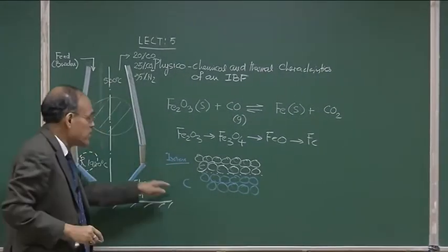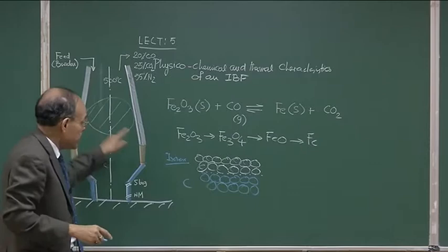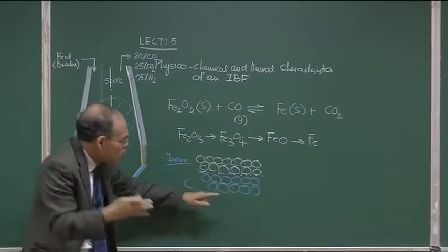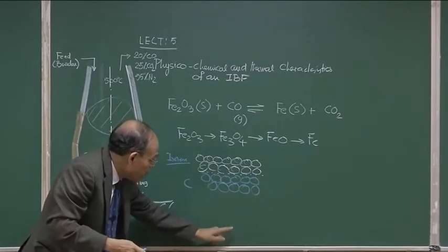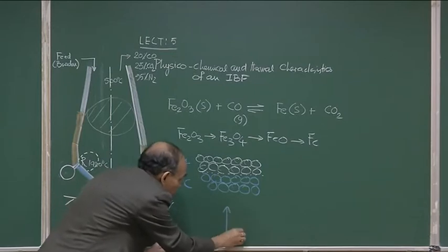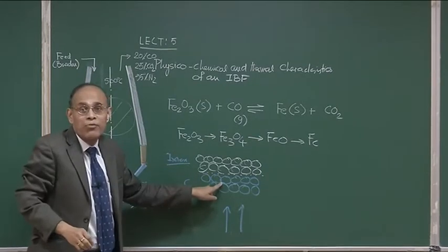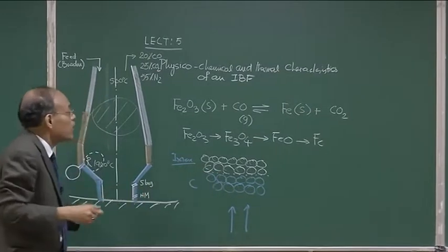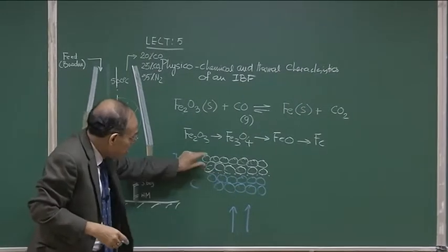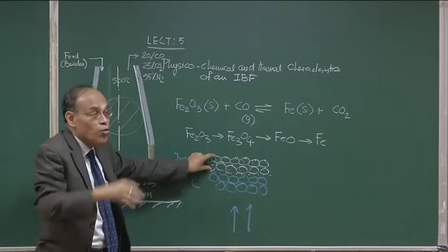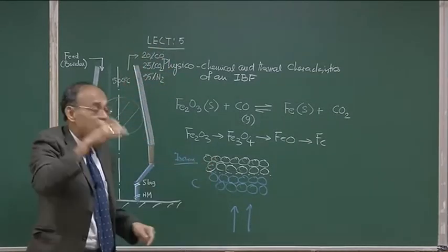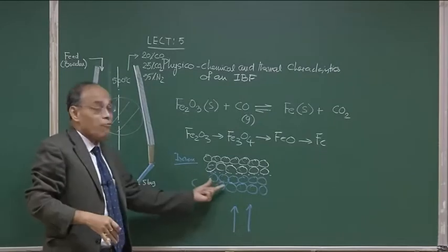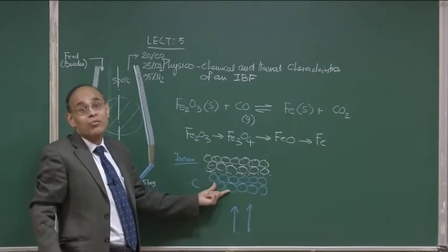Then what happens is, because it is a high temperature region and because it is coke, even though some carbon dioxide is there, as the gas is rising up it flows through the hot bed of carbon. That entire thing gets converted into carbon monoxide. So this layer of iron ore, stacked up in alternate layers, is progressively exposed to a very intense environment of carbon monoxide.